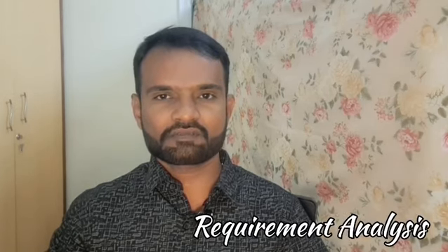So this is how I would like to break down this session, and I want to walk through requirement analysis as the first topic. Requirement analysis is basically capturing the system level requirements. It indicates electrical, thermal, EMI, EMC constraints and derating guidelines, because any component gets derated over a period of time.